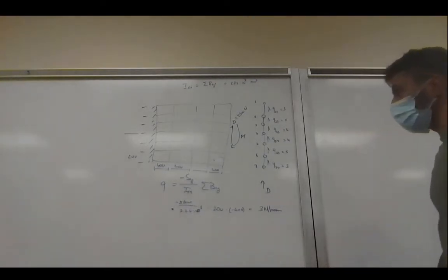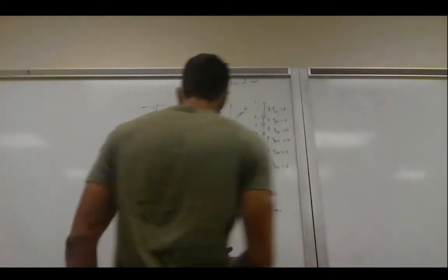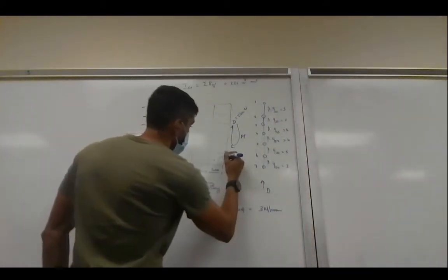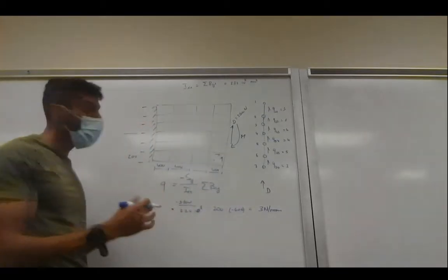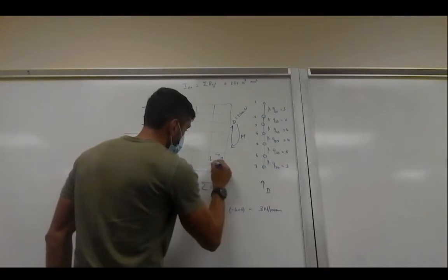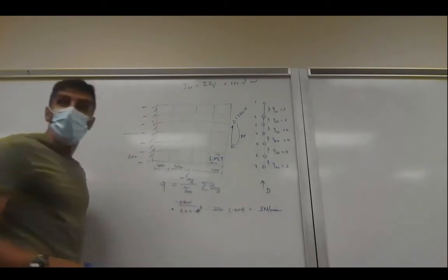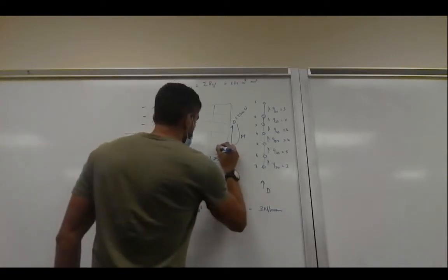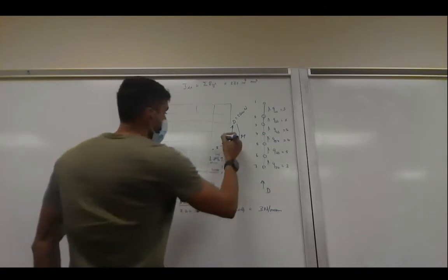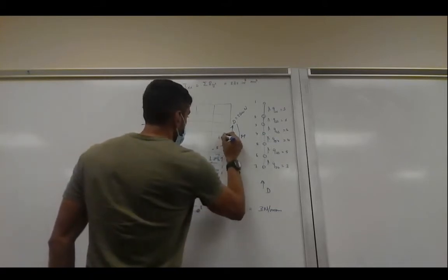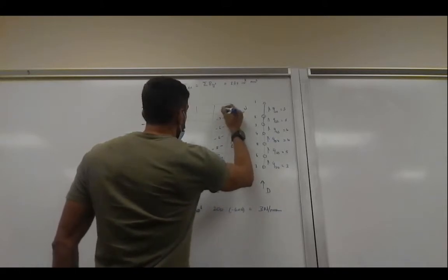Okay. So, and then the next question was, so now we have the shear flows. And basically when you have the shear flows, it means basically in this panel, because you have the equilibrium, so if you have shear flow like this going up, the second, because you have panel equilibrium, the shear flow must go into this direction. So this is all 3 Newton per millimeter. And then this is all 5. And I'm gonna just draw the lines vertically, so this gap. So this will be 6 going in this direction. This is 6 going in that direction, 5, and 3.